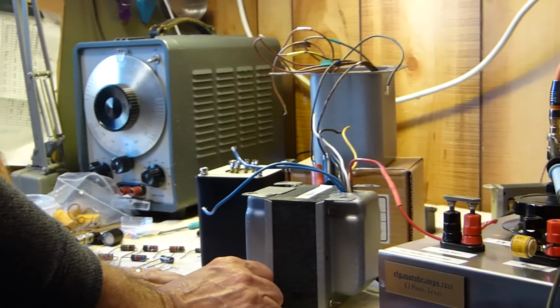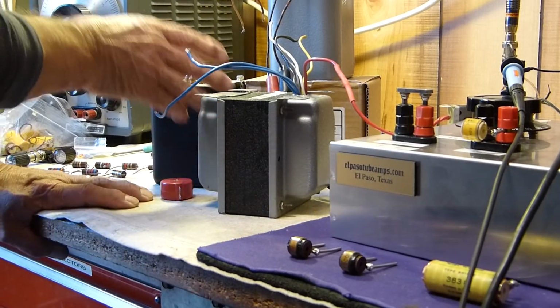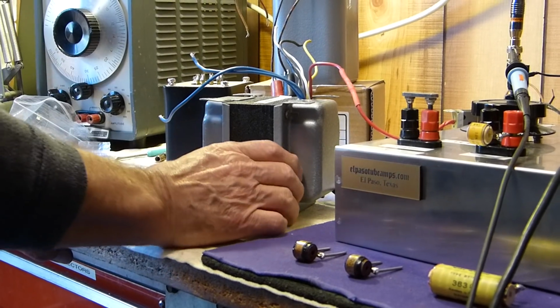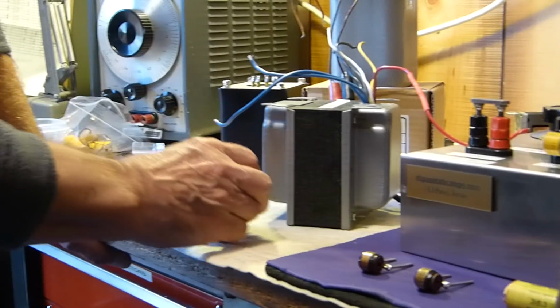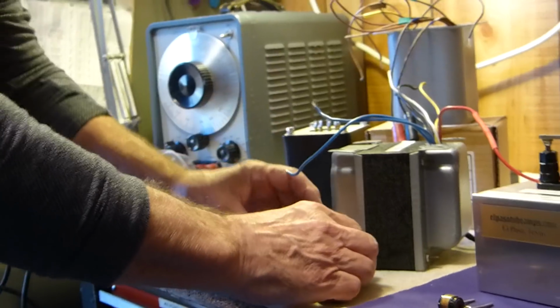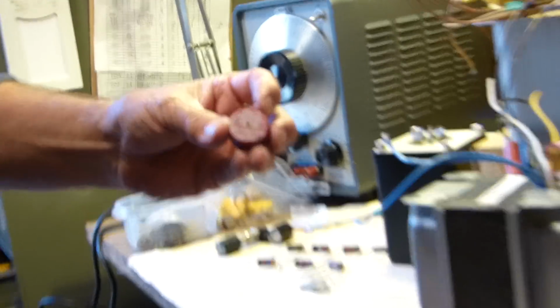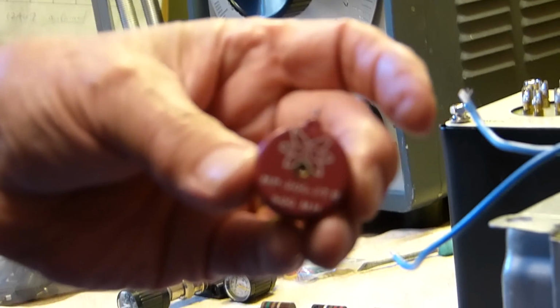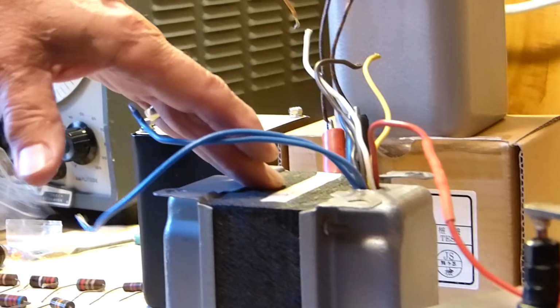So I have found out that this is actually quite a reliable way to measure the inductance of these big guys and get the same number every time, and get a number that agrees with my little standard inductors. There's the 17 henry, there's the 1 henry, there's another one over here that's 500 millihenry. It does the same thing. It'll measure just as accurately, and then I get what I expect. I expect these to be about 20 henries. This one surprised me at 40. This one measures about 20 henries too.